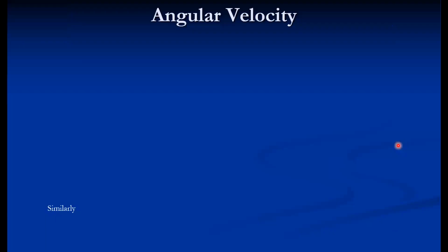The first term is angular velocity. Angular velocity generally exists if there is a rotation of the fluid particles. So in case of rotational flow, this angular velocity exists. We already discussed the rotational flow. The flow near the boundary is always regarded as a rotational flow. So there, the normal velocity gradient exists.